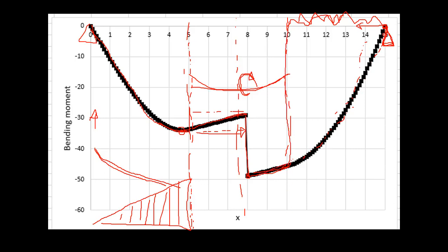Here also within 10 to 8, your bending moment reduces its magnitude. Why? You don't have anything, so the effect is going to reduce gradually. But from here to here, you have a loading. Don't think of it from here, you will get confused. It should reduce more and more. No, think of it from here, after you pass the halfway of the beam.